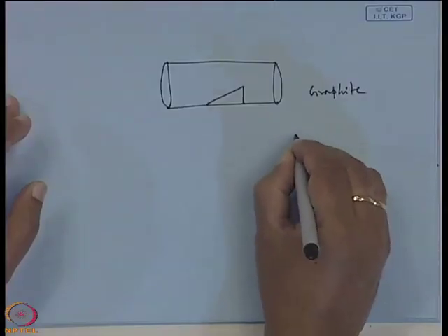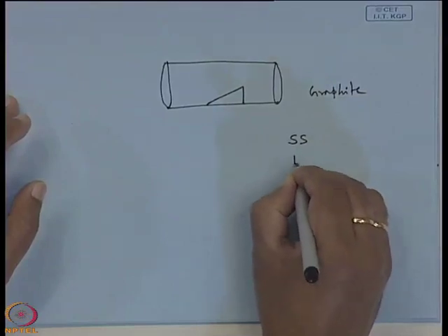It is basically stainless steel which is used, one thing. Another is the Inconel. Inconel, you know that it is basically an alloy which can withstand very high temperature without its degradation, because you cannot use anything which will react at that temperature with oxygen. So, one thing is the stainless steel, SS, another is the Inconel.